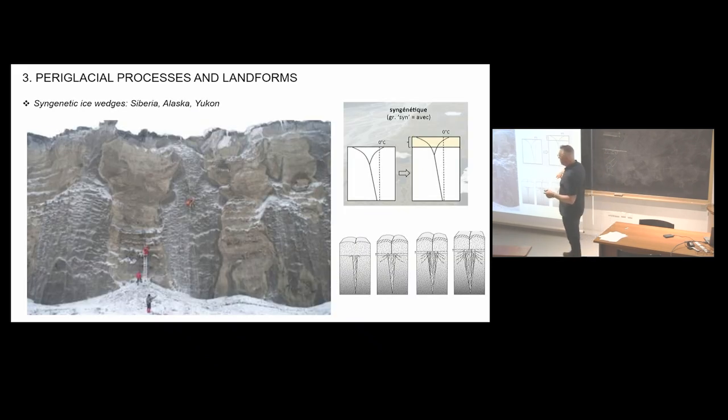Okay, so let's say we thaw this whole thing. If we have 80% ice pore volume, the surface will be something like that. It's an extreme that I'm showing you, but it's to show you the impact of, for instance, ice wedge formation, cryosuction, and ice layers development, how much ice we have, and the topographic changes that come when we disrupt these things.